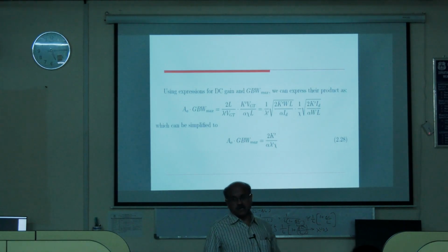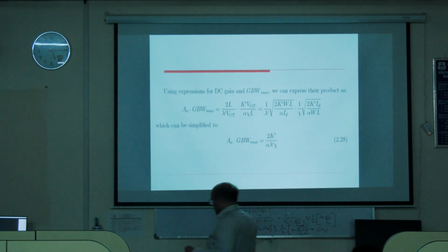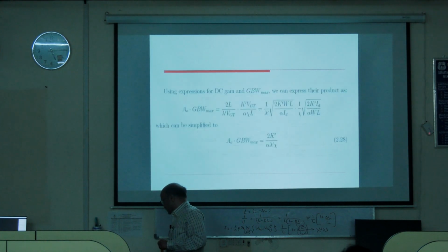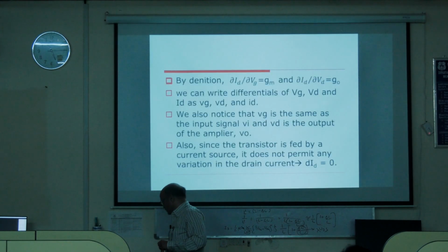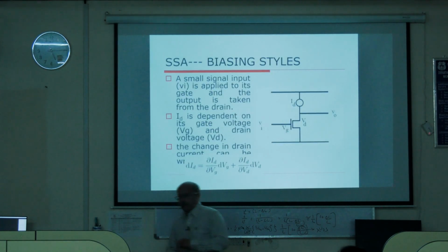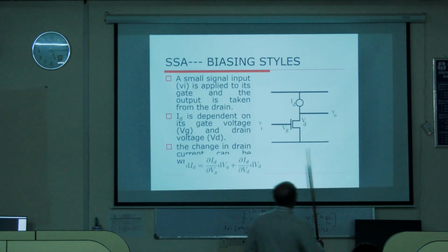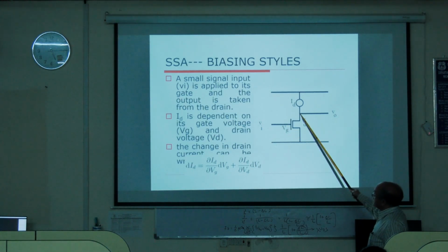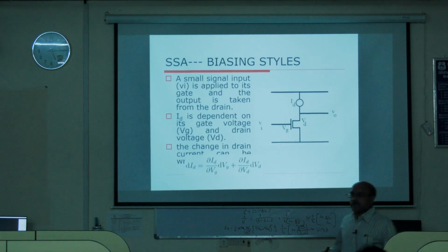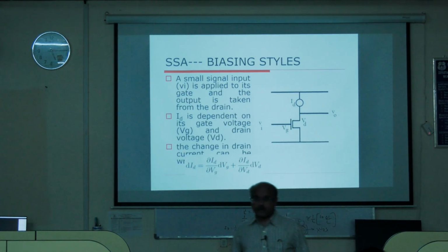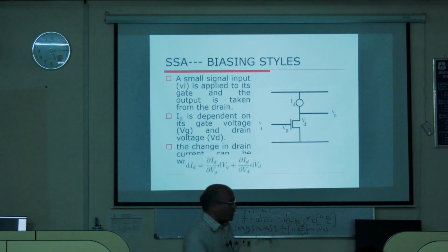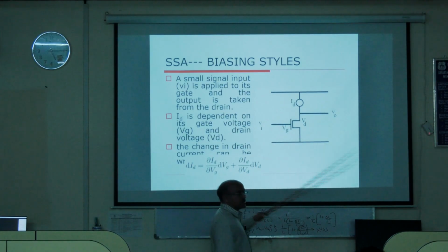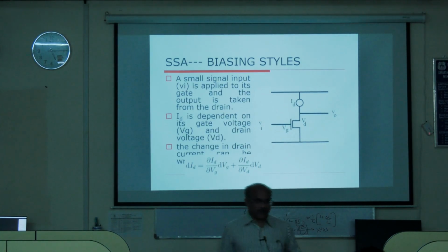Not only that, in the common source amplifier, you can also see that between the gate and the drain there is CGD, right. This capacitance CGD, now where I am trying to take output here and this is the input, but between the output and the input there is an impedance in terms of capacitance here.